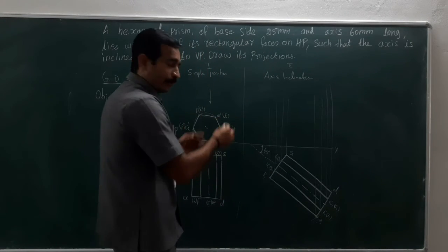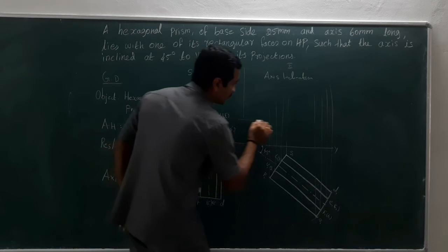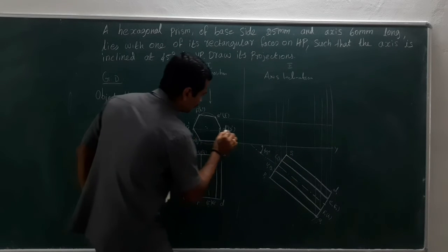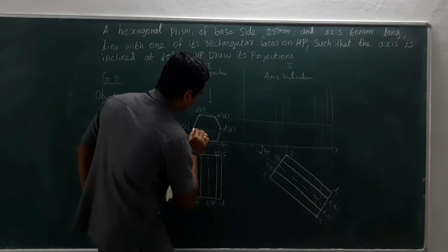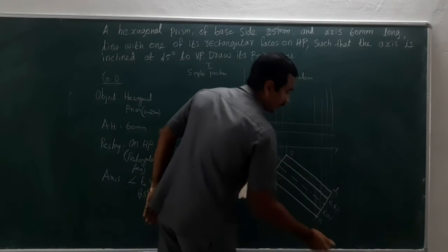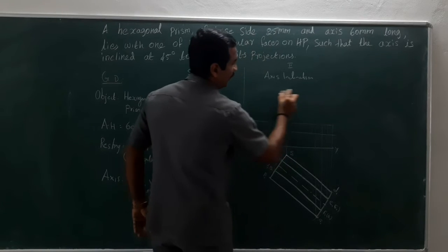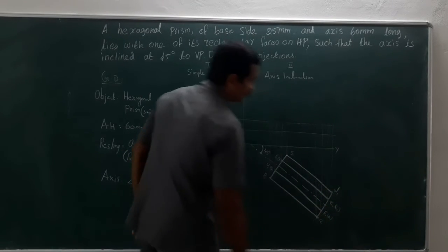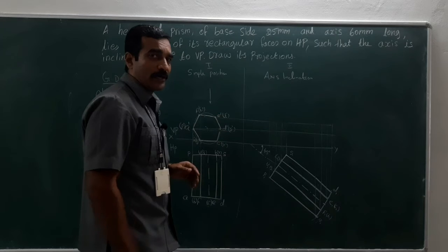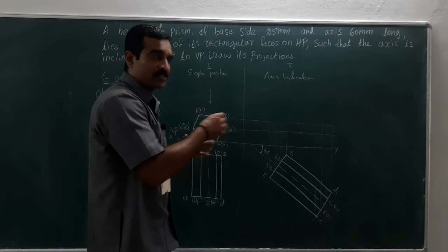From the front view, draw horizontal projectors. Now I got a box over here, so within the box only I am going to get the final front view. For which allow to see the merging points, that is nothing but the meeting points, intersection points.